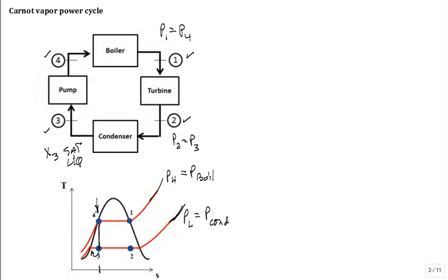It stays on that high pressure isobar, and it shifts way down such that I still have isentropic, constant s, isentropic increase in pressure through the pump. So it has to stay at this level of s, and there is state 4. Talk to me about the temperature at 4 now that it's shifted. Did the temperature of 4 go up, down, stay the same from where it was when it was Carnot? It went down.